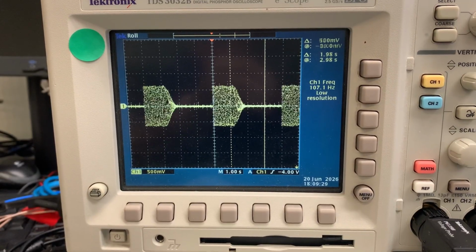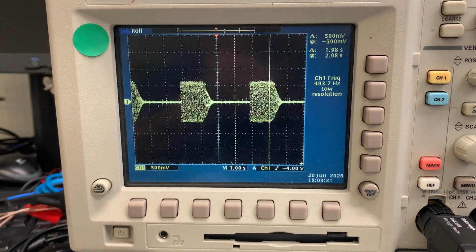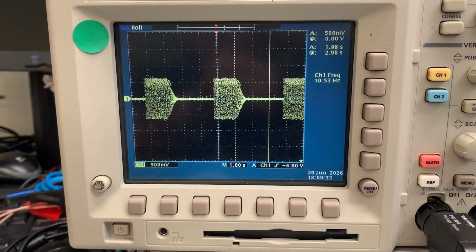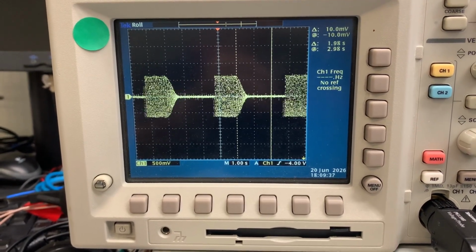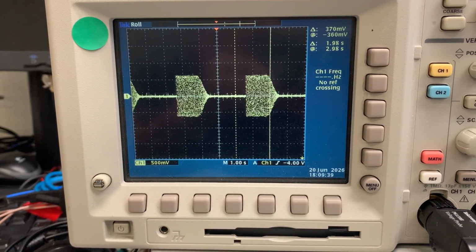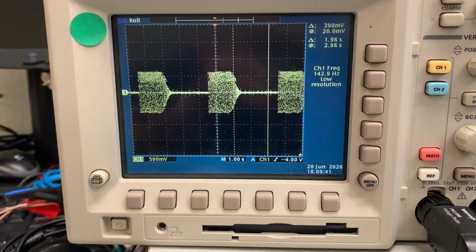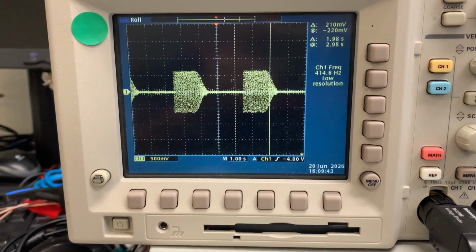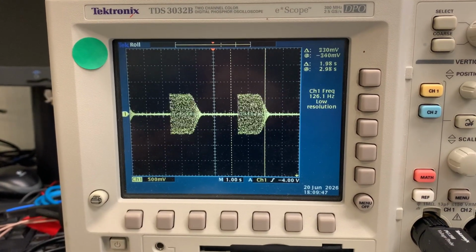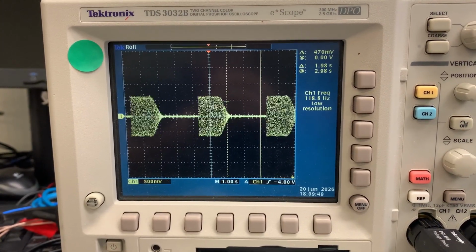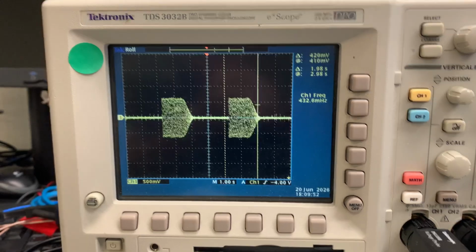The output of the DDS goes to an FIR, the FIR we designed last time together, and the digital output of the FIR goes to a DAC development board, and then the output comes to my oscilloscope right here, and another output goes to the spectrum analyzer that I will share with you later. So let's look at the time domain.